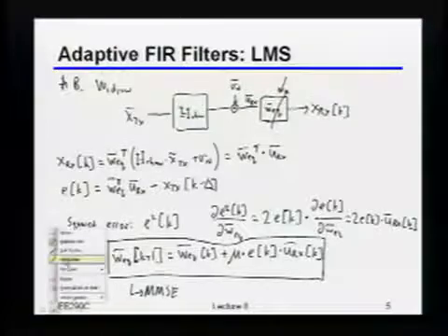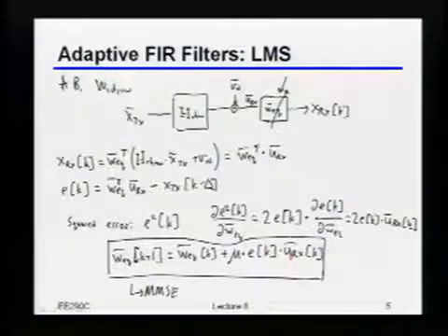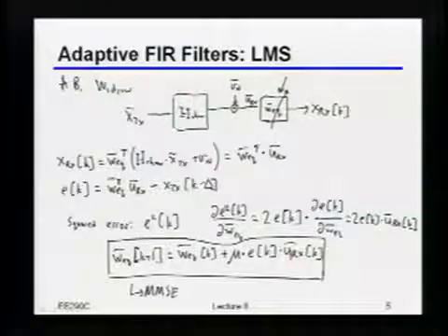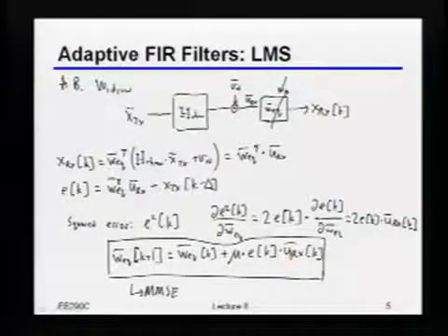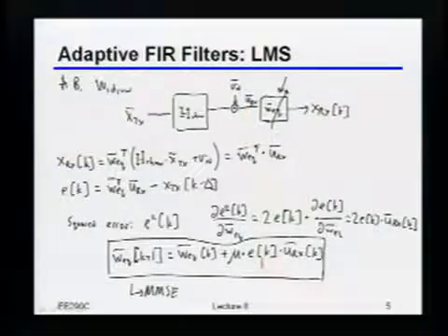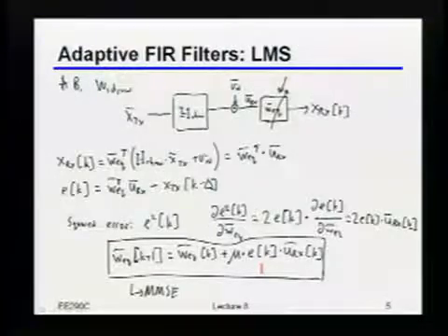What you're really doing is taking the error that you saw on this individual sample, but correlating it not just with the input to the equalizer at that particular sample, but also with previous inputs into the equalizer. Because if you think about it, since what you're trying to do is create a filter, you need some information about, over time, what errors were being created by the channel. So this E of k, even though it's the instantaneous value, I want to know how much of this error came from the previous bit, how much came from the bit before it, how much maybe even came from the bit that will follow due to precursor.